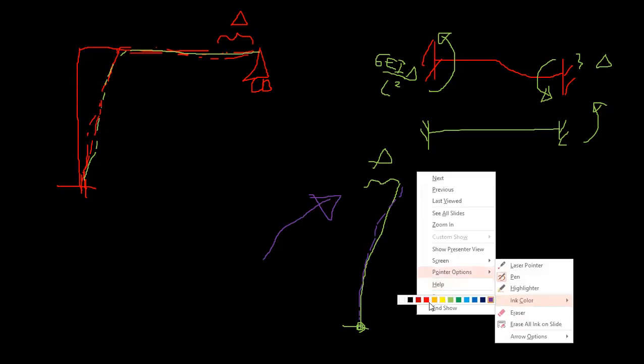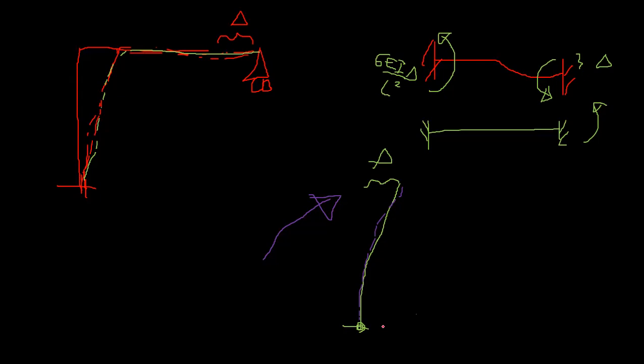To take it back, he should apply a bending moment in the other way. So this is my fixed end moment. Compared to this joint, this part has moved in this way. It's always relative, doesn't matter what actually settles.